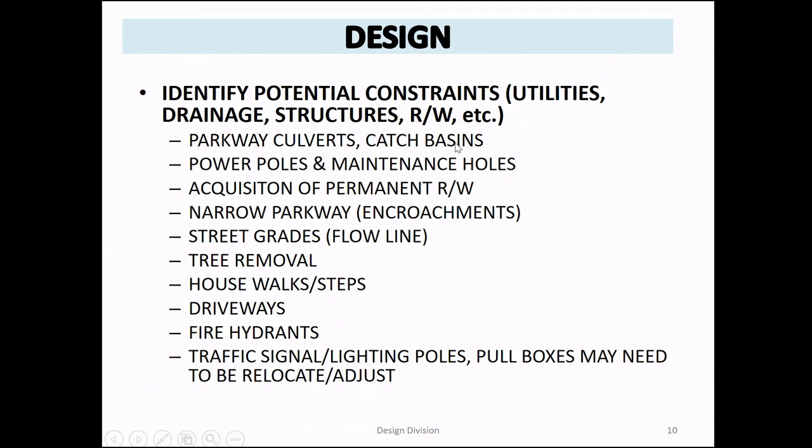Keep an eye on catch basins. There are many things we can do around catch basins. We don't have to have a flare. We can construct a curb, but for that you'll have to have a detail, not just call out the Caltrans standard plans. There are things that we can do to modify that standard plan to go around catch basins, power poles, manholes, maintenance holes.